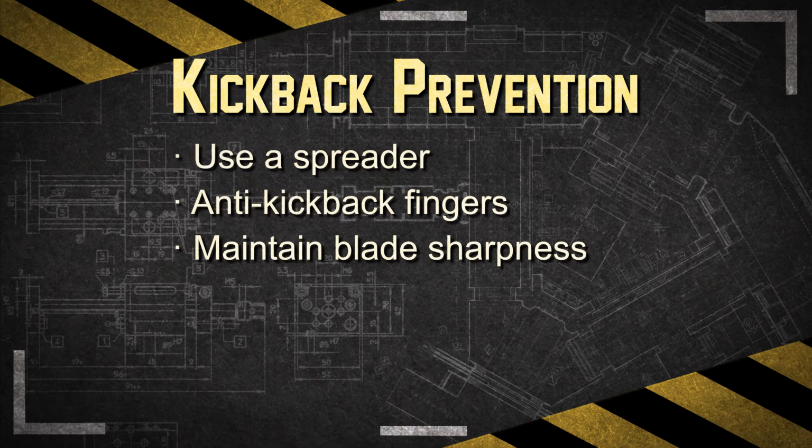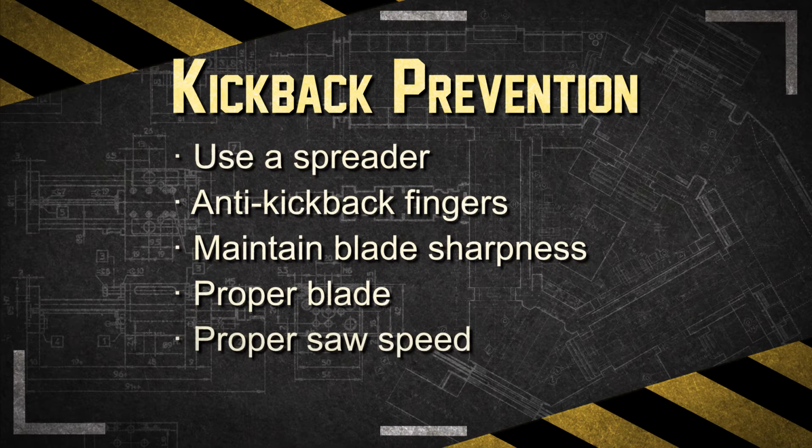Always sharpen and maintain your blade. Use the proper blade for your particular type of cut. Operate the saw at a speed specified by manufacturers, and position yourself to the side of the saw blade to avoid being in the line of fire.